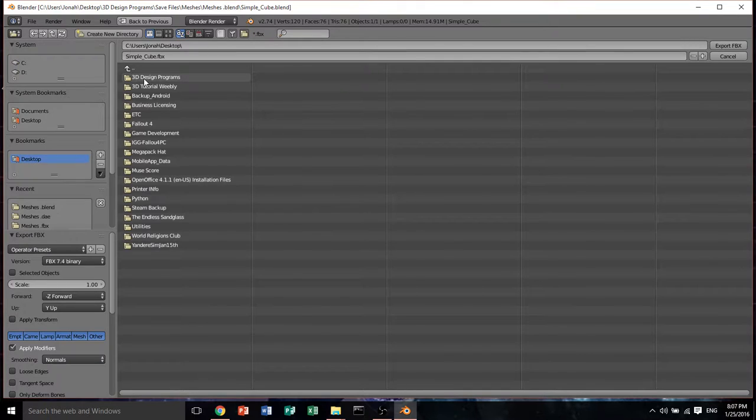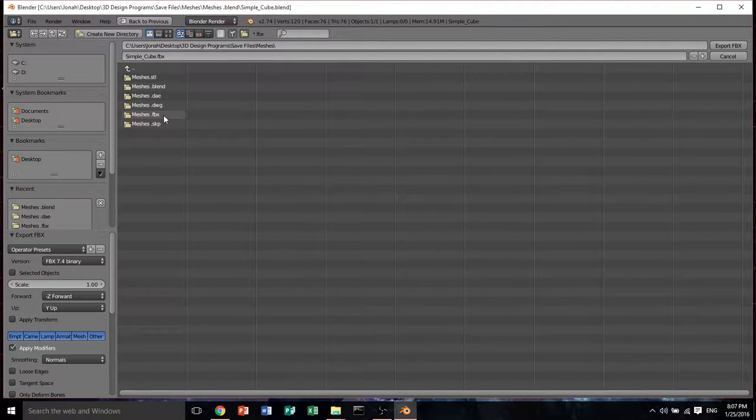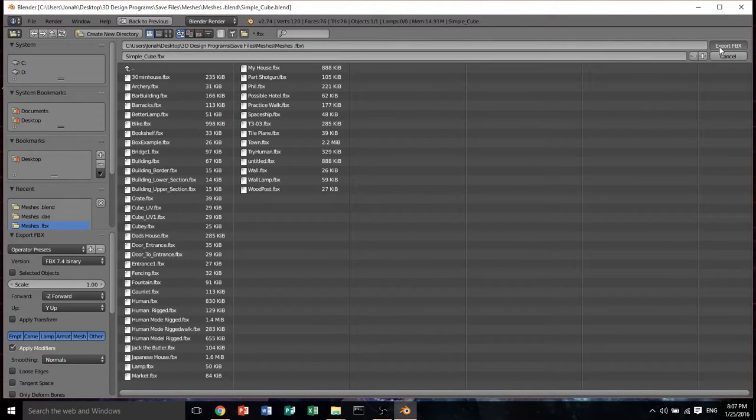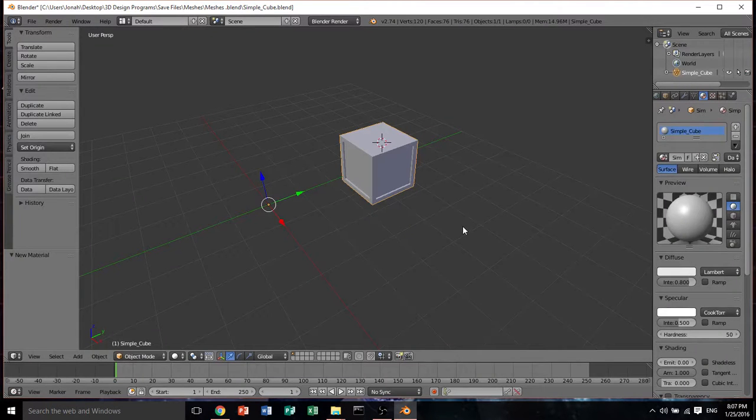Some important key information is why I go through Blender before I go to Unity 3D. To properly texture in Unity 3D, you have to UV map, which you can't do in SketchUp, but you can do in Blender. Another reason is renaming the material name, so that each object has the same material, and when you move in your mesh, they're not all separate parts.